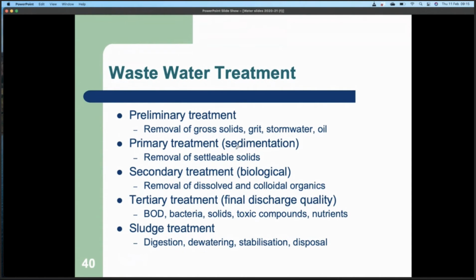And then you have the options of, like it says there on the slides, stabilization or straightforward disposal or digestion. So one thing that's always taken quite commonly in most places in the world, I think, is digestion, which simply means that you consider the sludge as another organic waste source. And this source, and we get back to that later, is relatively uniform. It lends itself to anaerobic digestion. So you put it through anaerobic digestion, you reduce the polluting concentration of BOD, and you get a bit of energy out of it. But again, we get to that later on.